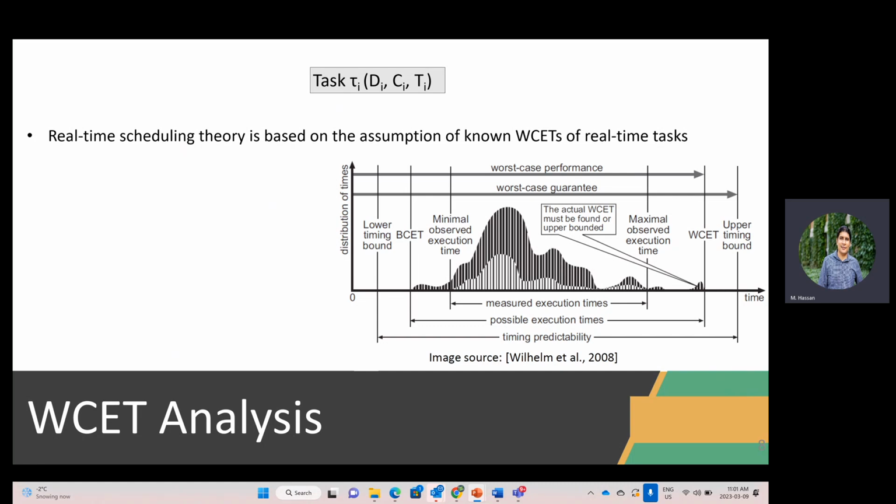And then afterwards, you see here that my upper bound is a little bit higher than the worst case execution time. Why? Because I add a safety factor just to make sure that any case I didn't account for, I'm already taking it further, right? Most certification authorities ask the companies to add a 10-15% safety factor on top of what they come up with. Good.